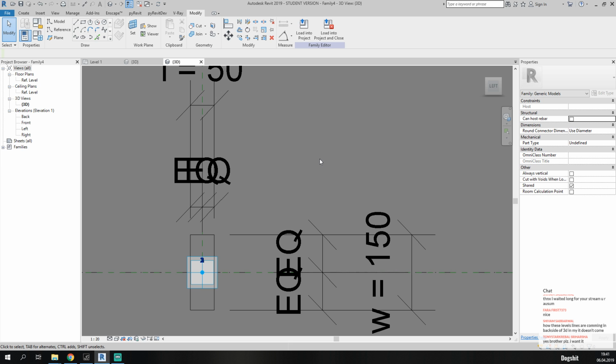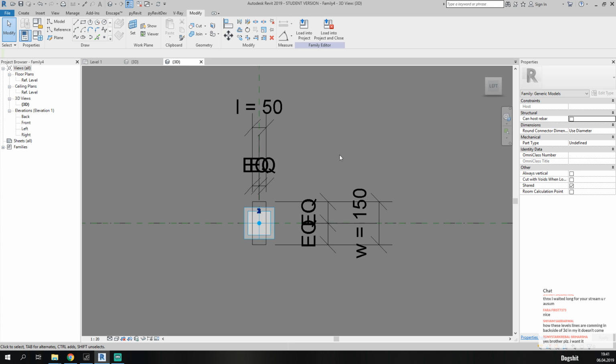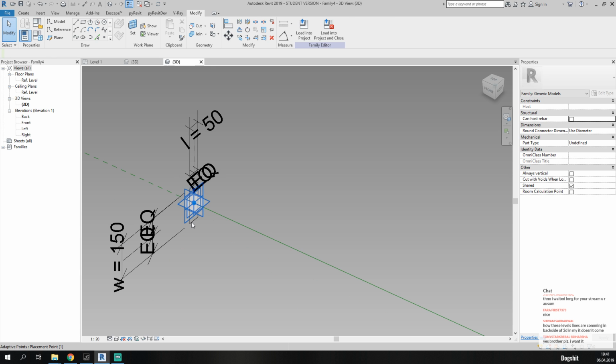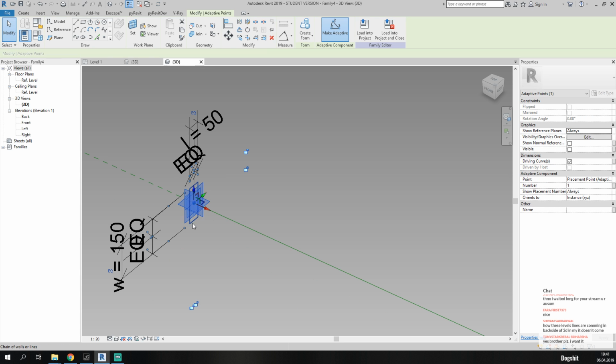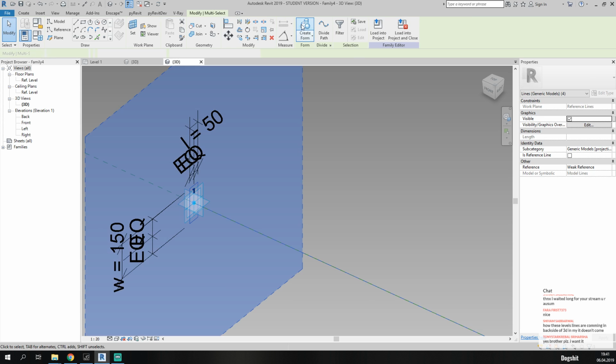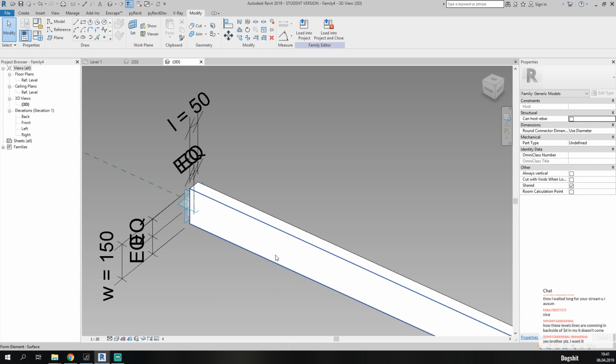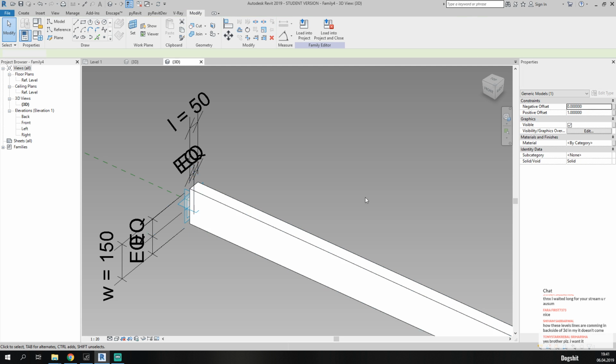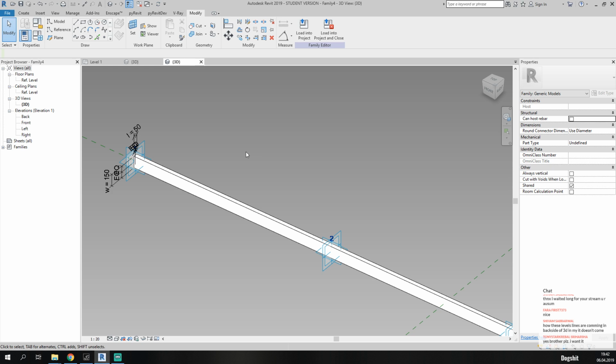So now we did everything right. So let's choose our profile, just tab key, and our line, and again create the form. And you should lock one profile. Just choose one of this profile and lock it. Done. So we are done. Let's load this louver inside our project.